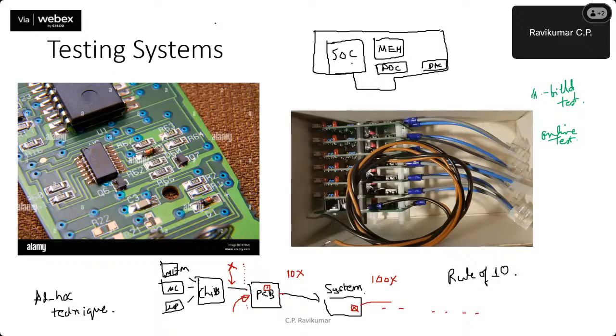So you may have seen, some people use jumpers. This used to be the most common way of testing systems a long time ago. So what they will do is, maybe, if this is a connection here, there will be a jumper wire, and it will be connected like this between these two, making a connection. And you can remove this jumper wire manually. So when you do that, these two get isolated. Okay. So here is a possible way to use it.